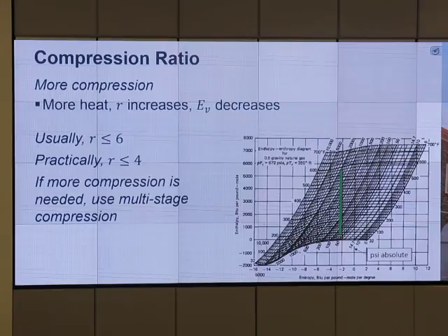And in the field trip, you saw that the exhaust gas can ignite and burn the system, which is a couple of $1 million. Is it $5 million? No, a couple of $1 million. It's expensive. Okay. So the compression ratio per stage, not the total compression ratio, should be less than 4 to not make it too hot.